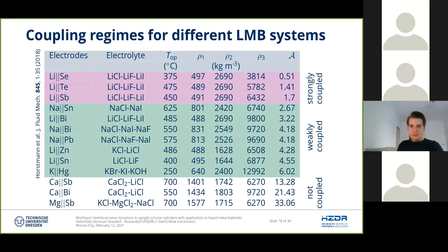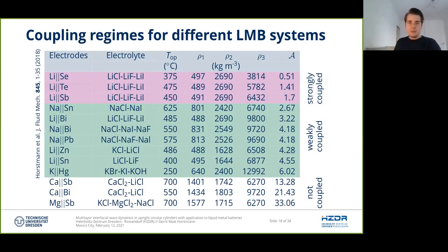In these experiments with the UDV, where you follow the interface with the UDV probes, you were able to reconstruct the interface, right? So for that purpose, instead of looking at the velocity, you were able to look at the echo signal? Exactly. Yes, I directly track the echo. Usually UDV is applied, of course, to measure axial velocities. But here I'm interested in the elevation of the interface. So I can directly track the echo to reconstruct the wave amplitude and the interface motion.